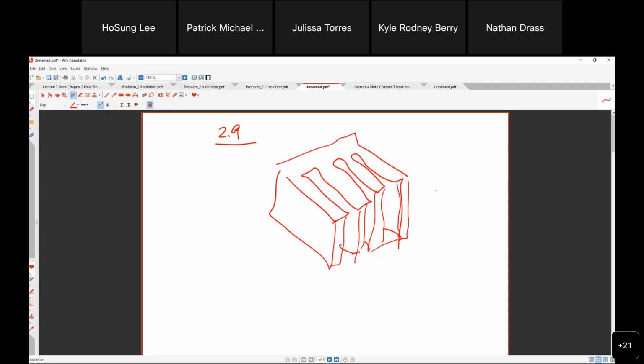pre-convection heat sink. We have dimensions. So as I mentioned, you can look up the single fin approximation actually. If you have a CAD, you can look at multiple fins, but you can design a single fin, and then the question is what would be the spacing? Optimum spacing. So for optimum spacing you have to look up